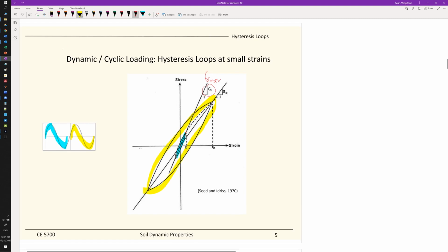So you see the sequence of the stresses, like you go this way. The stress strain curve development is you form the loops and then complete the loops, then you will stay on, and then you will have your second loops. And as you can tell, the loops just get larger and larger until you have enough deformations and the whole soil fails.